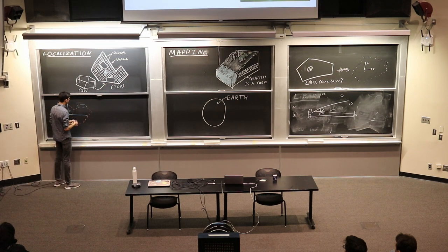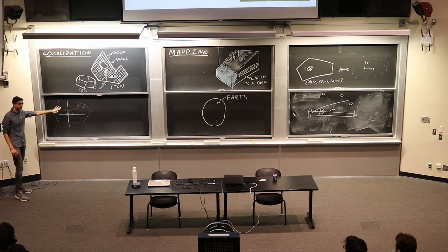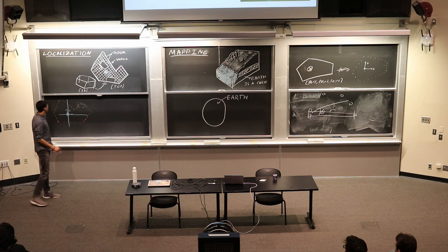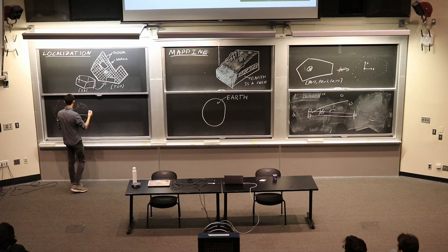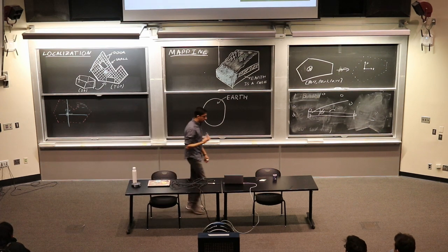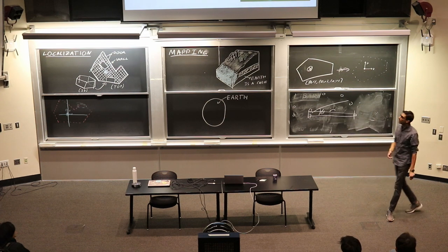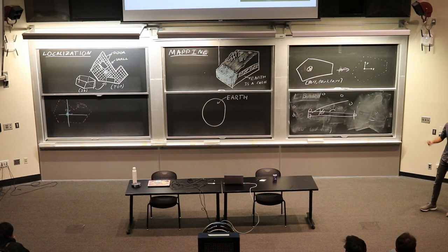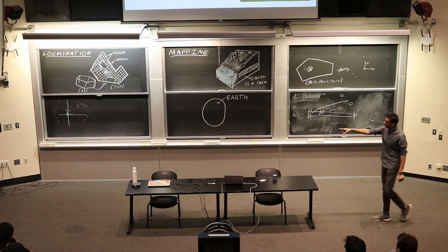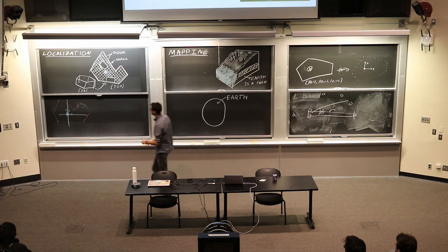But just for the sake of understanding localization, let's say we get this as our point cloud. And this is my origin point cloud. And let's say my map origin, let's put that arbitrarily here. It really doesn't matter what the map origin is, because what localization is going to try to do now, again, this is one type of localization. This is called LiDAR-based localization in a known environment. What we're going to try to do is take this point cloud and match it to our map. This is called scan matching localization.